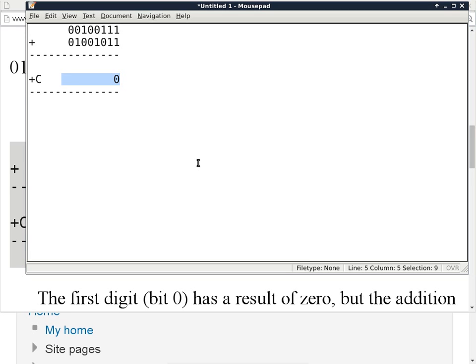And why do I stick a 0 there already? The 0 is not even calculated from anywhere. Why do we stick a 0 over there? It is already the least significant bit. If it is already the least significant bit, then it's not going to get a carry from somebody else's addition. So that's why it's a 0 over there. Is that okay? All right.